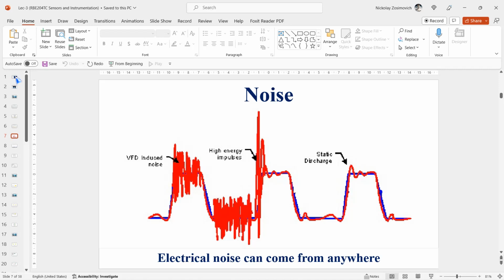Thermal noise is an example of white noise. Another important type is 1/f noise, a collection of noise phenomena with a spectral noise power proportional to 1 over f to the power n, with n between 1 and 2.